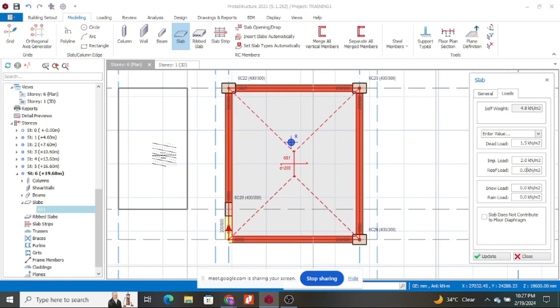Okay. So when you do all that math, you will realize that it will become height times 10. That is the loading of water. Now there is something we call quasi-permanent. I think you can read the Eurocode on the same. When we are designing for water, we can consider it to be a partially permanent load, not a live load.